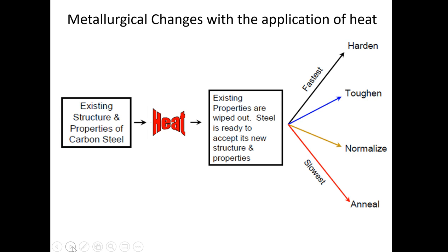When you've taken this cap and pressed it on the part and fired it for a certain amount of time and you leave it there, we already understand it's very important to keep the caps really nice and cool, but those caps can quench it as well. It can take the heat away really, really quick. So I have programmed many tail outs, and I call them tail outs because my journeyman called them tail outs, where in the final stages of cooling, I actually gave it a little extra heat to slow the process down and leave the area around the weld in a softer condition than you would normally get if you just left it alone.